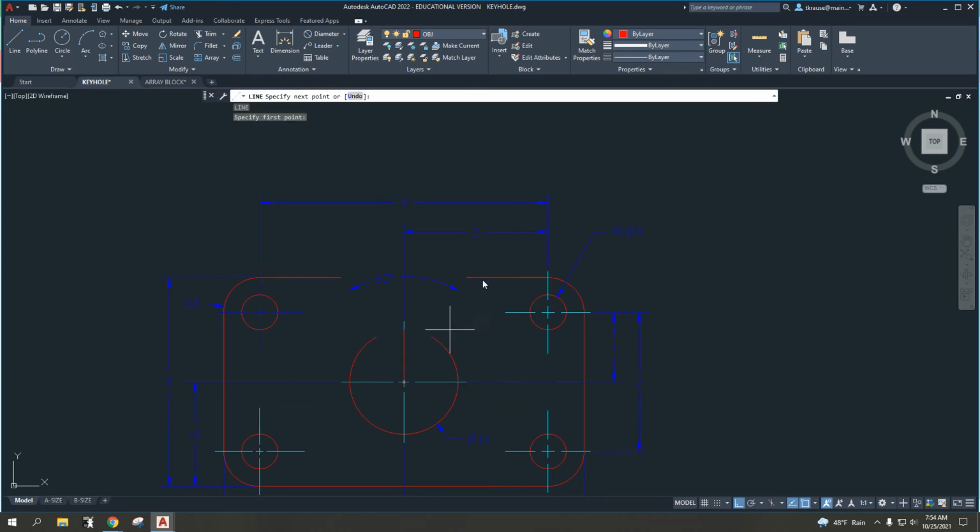A lot of times when I'm drawing a line, I go at... Okay, let me turn off ortho again. So ortho tends to have this coordinate system. And if we take a look at the coordinate system that's attached to my cursor right now, it's currently saying 3.1535, and that's our distance. And then you'll see the angle.